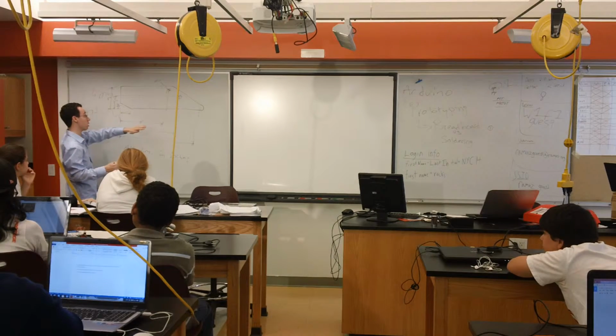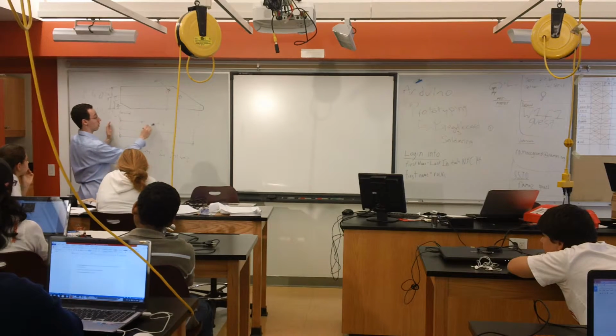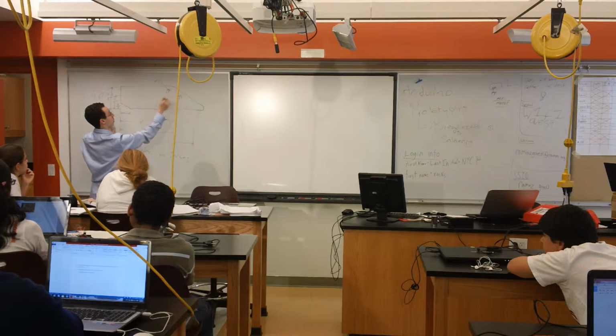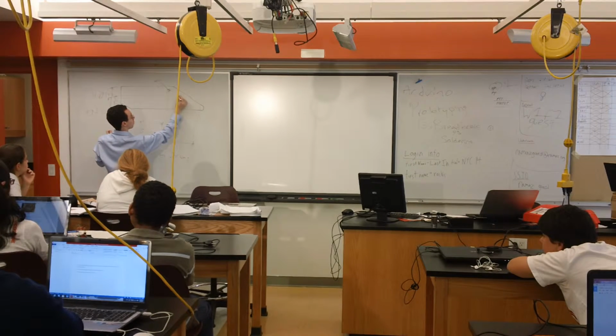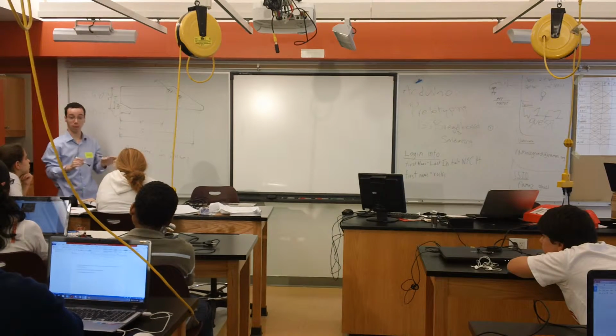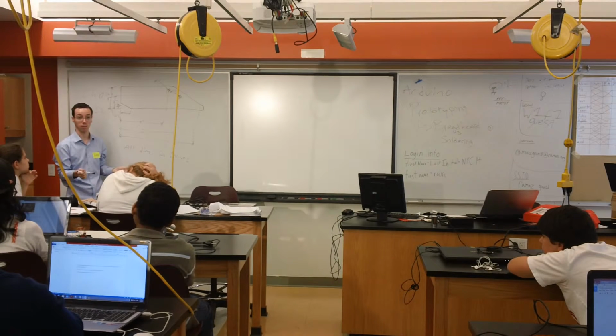So if I were a machinist, or if you give this to a machinist, he or she can go, okay, I go 5 inches this way, 3 inches up, and then I put in a 1 inch diameter hole there. They know exactly where it is, they can repeat that 1,000 times if you want. Any questions on that? Okay.